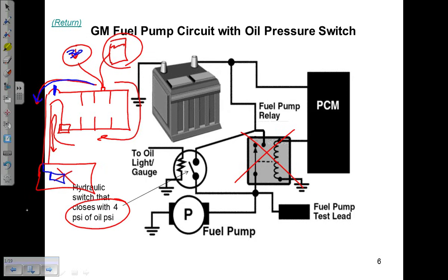Okay? So we're doing a fuel injection service, and we remove the fuel pump relay to keep the pump from running. Obviously, you'd want this pump to shut off. You would not want the pump running and pushing fuel up to your pair of needle nose vice grips that you have pinched on that line. Because some of these injection services, you'll run the car for 20, 30, 40 minutes before it runs out. Again, this is an externally pressurized container. It takes a while for this to run down, and the car's going to run for a half an hour. Imagine running a fuel pump for a half an hour up to a pair of vice grips, and it's basically a dead-headed situation. You're going to burn the pump up.